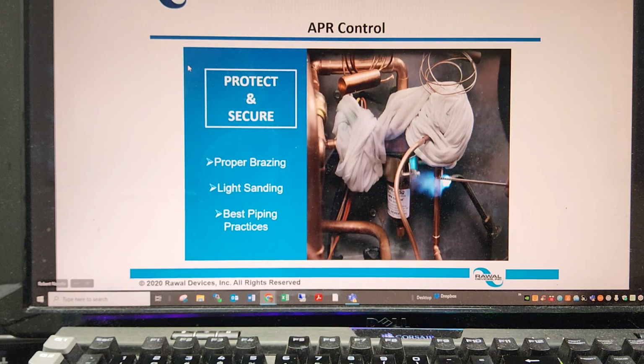If you want to, do your best, like I said, best piping practices. Whatever has worked best for you in the past is going to work. Okay, that's fine. We do recommend a couple quick scuffs. Nothing crazy. Sweet. And again, just make sure you follow your best piping practices. We just want to make sure it's a clean install and nothing is going to be rubbing against anything else. Sure. We have a lot of calls about those capillary tubes on the sensing bulbs leaking because they're swinging in the air and rubbing against something. So just make sure nothing is going to be rubbing. Yeah, long radius elbows, things like that. Exactly.